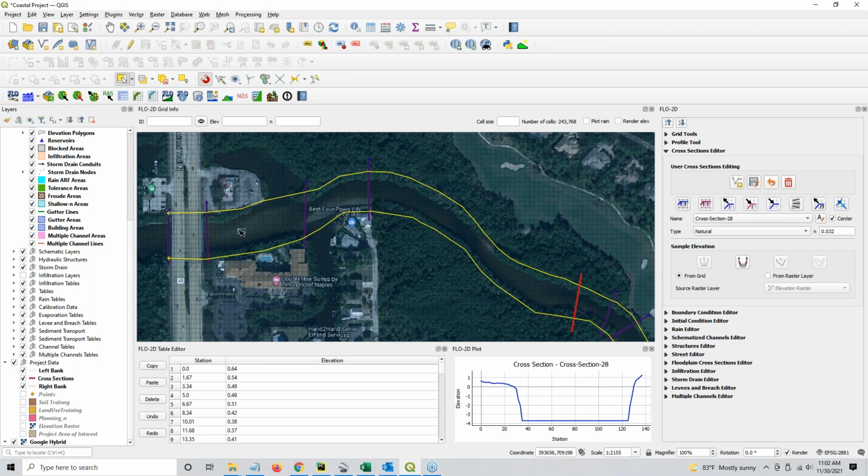So these sandbars are going to rework themselves, and these cross sections are not going to hold their shape. So the reason I don't bother trying to get a perfect cross section in here is because I'm more concerned with getting the capacity of the channel. And if the water is moving fast enough down this channel that it can rework these bars and mobilize that sand, then the capacity of the channel will be a little bit more realistic if you represent it like this. So that's why I don't try to get these bars perfect in here.